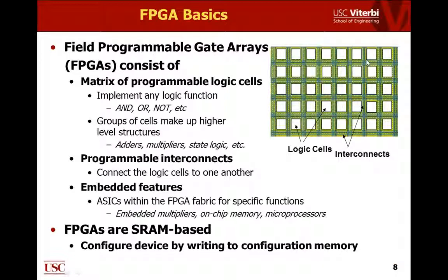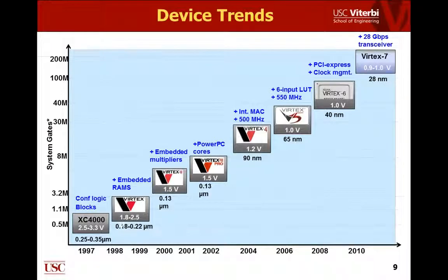That is the basic idea of using these FPGAs, and configuring these devices means that I'm going to be writing something into the local memory of what are called LUTs, or lookup tables, you have in those implementations. The technology has advanced quite a bit over the years. In the last 15 years, the state-of-the-art devices in the market today are extremely capable devices. Very high data rates can be sustained by them.